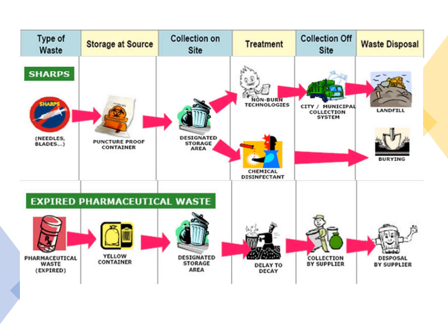So it has to be inactivated through non-burn technologies or by the use of chemical disinfectants. If the treatment is non-burn technologies like pyrolysis and the use of autoclave, sterilization of the sharps waste is achievable. And once they are sterilized, they can be collected by the municipal collection system and can be discarded into the